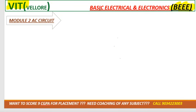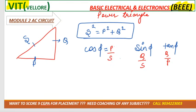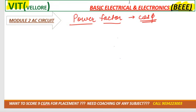Now see, you have listened to one more term, that is power factor, right? Power factor is nothing but cos phi. So if you calculate cos phi from the power triangle, then power factor is P by S. Some students misunderstood that it's phi. No, it's cos phi, cosine of the angle between voltage and current.